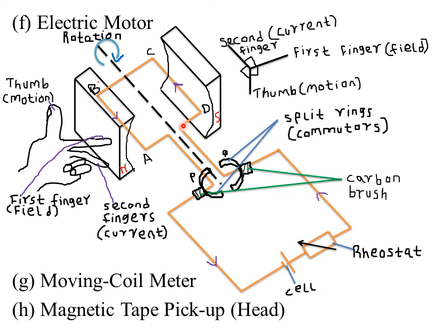So four ways in which we can improve the working of an electric DC motor is: one, by winding the coil on the soft iron core, because the soft iron core becomes magnetized and concentrates its magnetic field in the coil. So this increases the force on the coil.